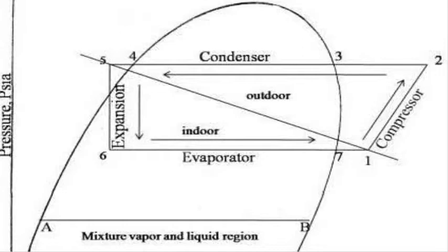When the evaporator refrigerant has boiled completely to vapor, it's now saturated vapor at point 7. Some compressors cannot pump liquid. If one does pump liquid, it will be damaged. This is why we need all the liquid refrigerant to boil by point 7. After the entire liquid refrigerant turns to vapor and passes point 7, superheat occurs. Superheat is between points 7 and 1. Superheat is life insurance for the compressor. It makes sure the compressor does not pull in liquid refrigerant from the evaporator.